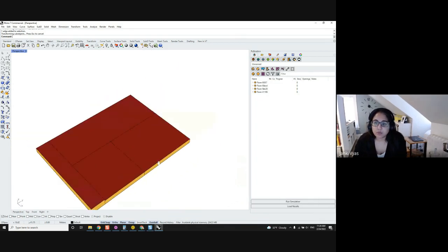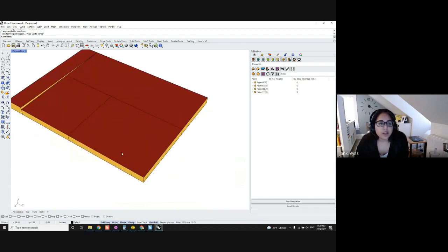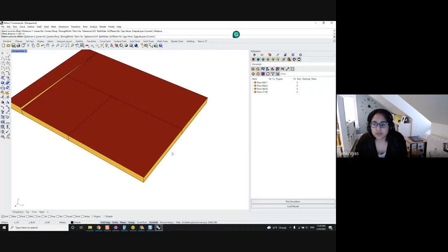And then also, if you want to split rooms, say you wanted to create a perimeter core zone, you can start by using the Rectangle Corner to Corner Rhino command and trace the room that you want to create the perimeter core zone in. Then use Offset and identify a distance. Say you want a 4-meter perimeter zone. Once you select that curve, it will offset 4 meters inside.